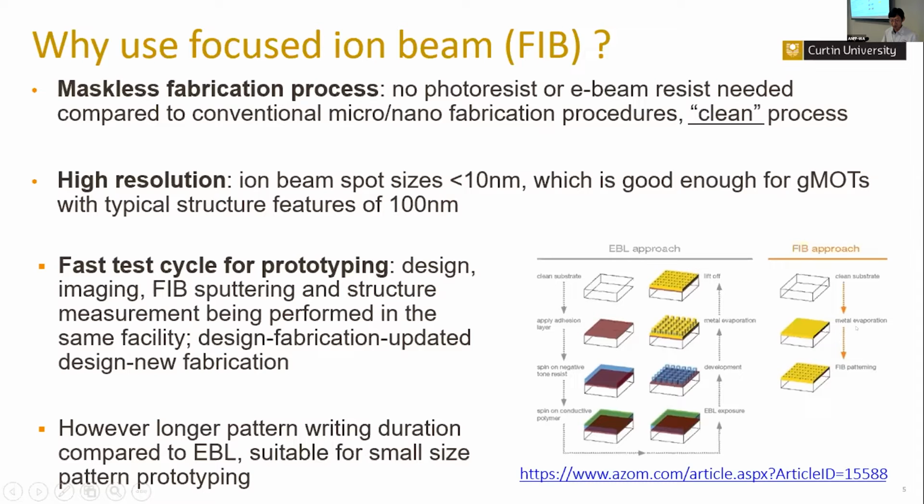Actually, for our project, we may not even use the metal evaporation process. We can just do patterning on top of the substrate. And so we can do a faster test cycle of the prototyping from design, imaging, sputtering until the final measurement in the same system. So we can do the whole process in a short time. However, compared to conventional EBL or photolithography, it has a relatively long patterning process. So it's more suitable for small size patterning and prototyping.